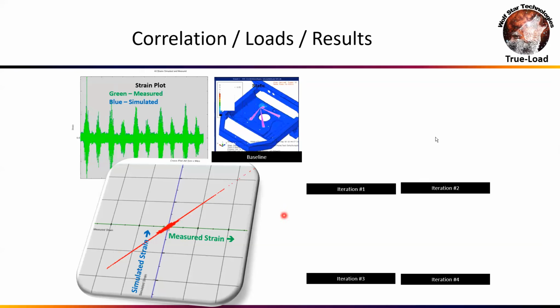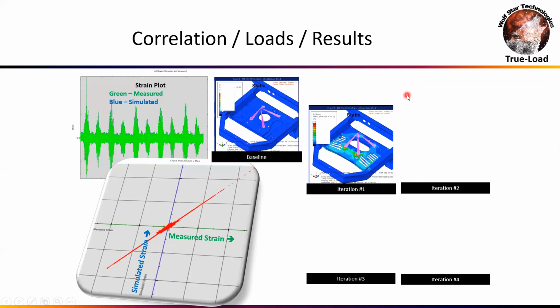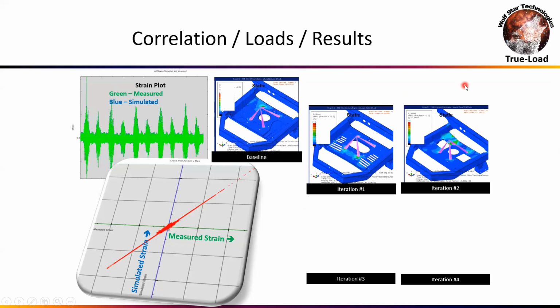And I said, perfect. Give me that FEA model. Let's take the loads that we've measured and run it through. So you can see we're getting very high stresses and strains on this initial design of theirs. And then working with the engineers there, we came up with a different design. Basically had 2 large holes, and the initial design was 2 layers of sheet metal riveted together.